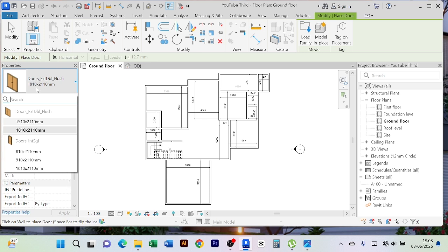That means I have my library, I've created it, I downloaded some doors, so I'll just use my library instead of going with these generic doors that may not give the best look to your desired design. So when you have clicked on the door, if you have the library, you come to this tab which is called load family.